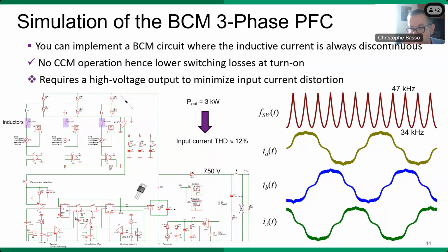This is an application example of this free-running technique, three-phase PFC. We deliver 3 kilowatts to a load, and we use one single switch, and the RMS current in the transistor is 3.8 amps for 400 volt AC, phase-to-phase, of course, with peak current reaching around 13 amps. And this circuit includes a specific circuit to limit the maximum switching frequency, and also what we call a watchdog, because this is a QR type of operation. So in case the restart operation doesn't come in time, then you have a watchdog restarting the circuit. It's a 10 kilohertz watchdog, and it's very common to classical QR converters.